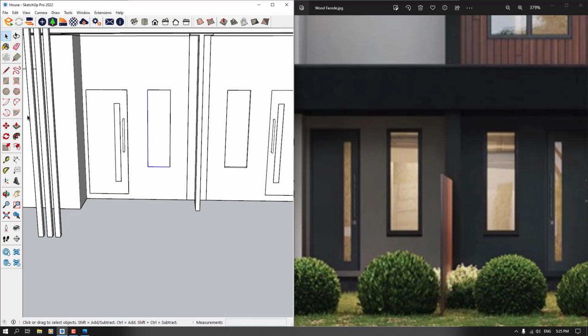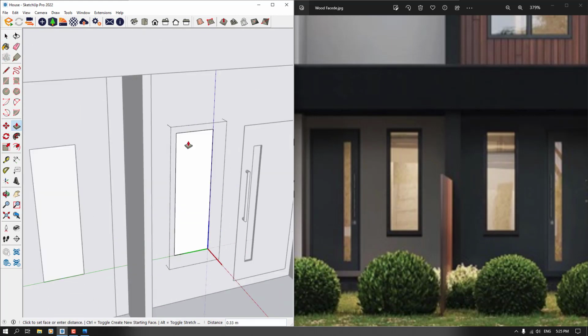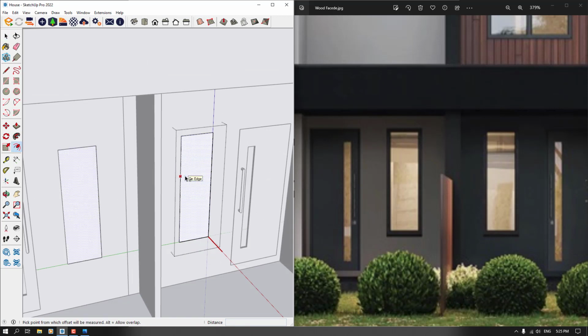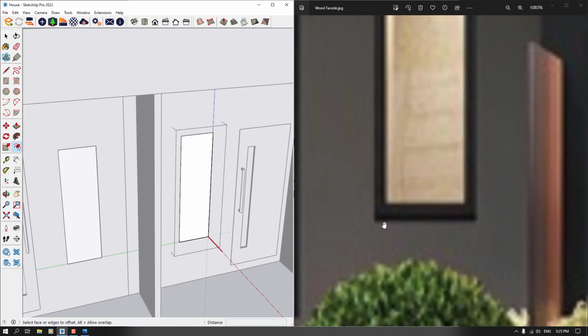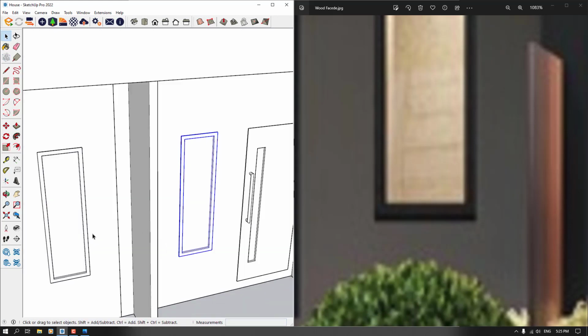I'm gonna enter it. I make some copy of it, flip along green direction. So I'm gonna click on it. I push it to the back side, something about 4 centimeter, and upside something about 1 centimeter. I'm gonna offset it. I think offset of this window maybe something about 5 centimeter, like that. And I'm gonna push it back about 4 centimeter. So my window is ready.